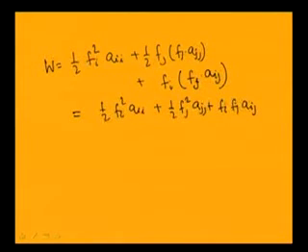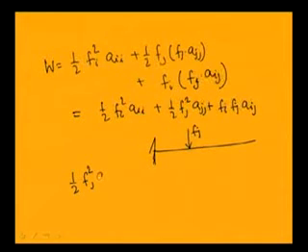Now, let us alternate the application of force. Let us first apply the force Fj and then apply the force Fi. So, if you apply the force Fj first, then the work done will be equal to half Fj² Ajj, and by applying a force Fi after that we will have a displacement of Aji.